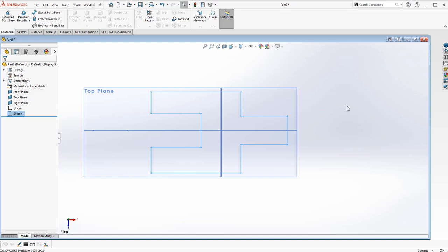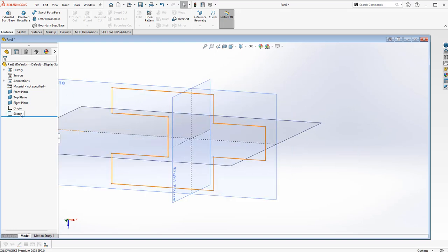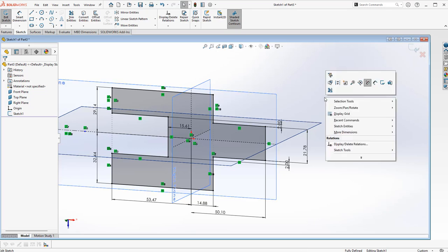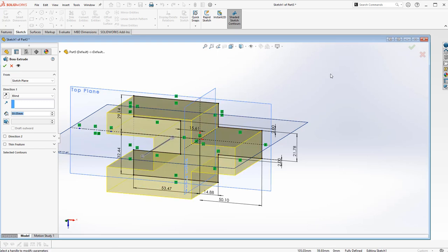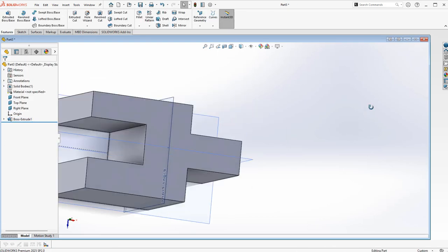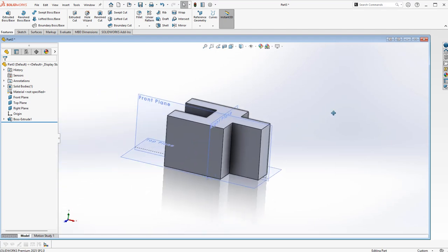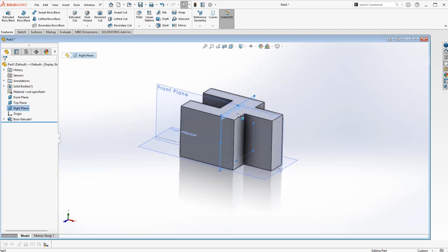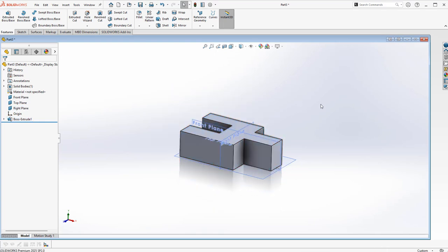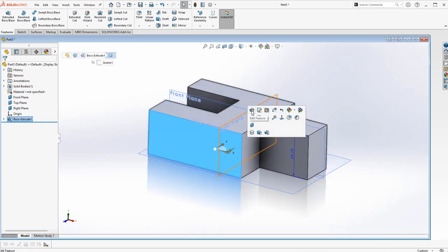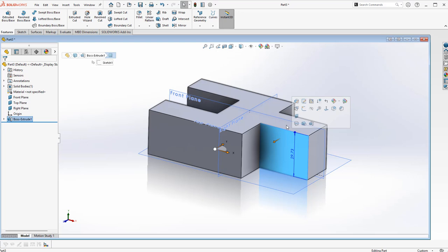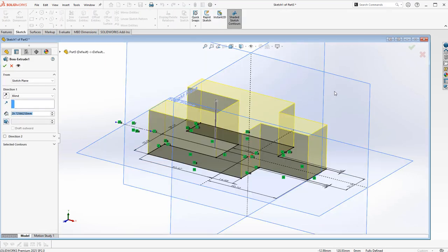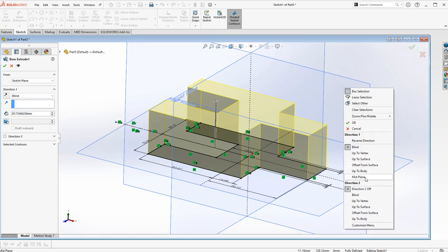So you don't technically have to check out of a sketch in SolidWorks to extrude something. You can just hold down and reach for extrude. And as you explore ways to move faster and think more clearly in SolidWorks, consider customizing this pop-up window to accommodate your needs. So I can edit definition on the feature. I can click in the graphics window and edit definition on the feature. In this case, I can hold down and say, you know what, I meant to hit mid plane.